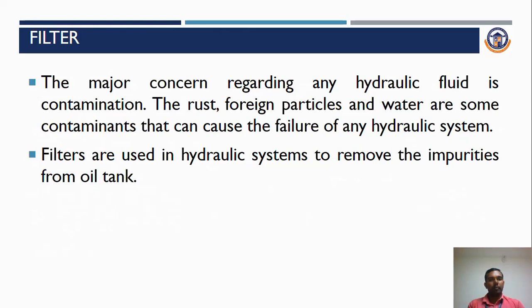Filter: the main purpose of the filter is to remove impurities from the oil tank. The major concern regarding any hydraulic fluid is contamination. Rust, foreign particles and water are some contaminants that can cause the failure of any hydraulic system.